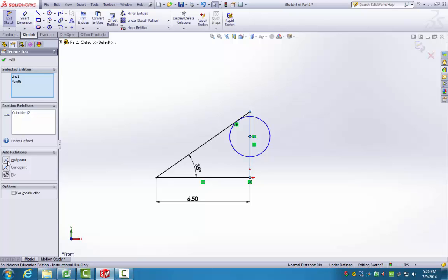If I can leave you with one final thought, it's when you sketch, make sure you use fully defined sketches always, and make sure that you really put thought into how these things can change, because oftentimes you may have a somewhat complicated sketch with only a few important dimensions, and you want to make sure that those important dimensions will change the sketch the way you would hope it would, and that all of the associated relations that you would assume are in SOLIDWORKS, which will allow it to adapt a little bit better.